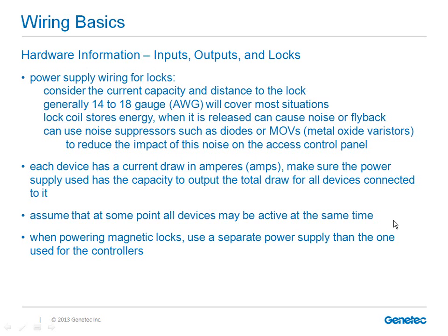A good tip in general is to use two separate power supplies when using magnetic locks. You want to use one power supply for the locks themselves and another one for the controllers.